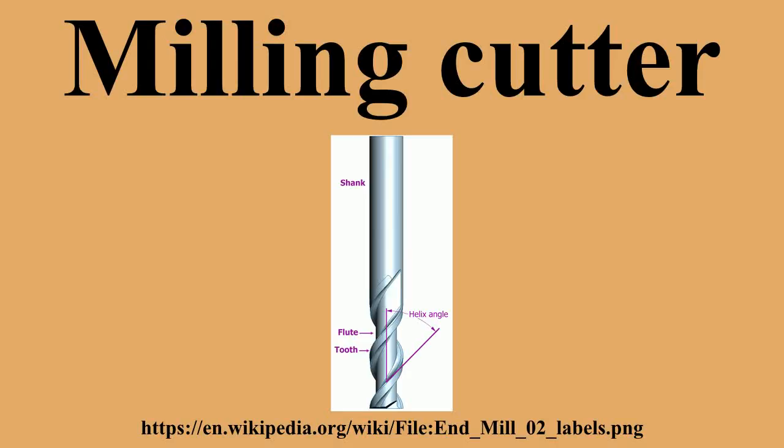In conventional milling, the chip thickness starts at zero thickness, and increases up to the maximum. The cut is so light at the beginning that the tool does not cut, but slides across the surface of the material, until sufficient pressure is built up and the tooth suddenly bites and begins to cut. This deforms the material, work hardening it, and dulling the tool. The sliding and biting behavior leaves a poor finish on the material.